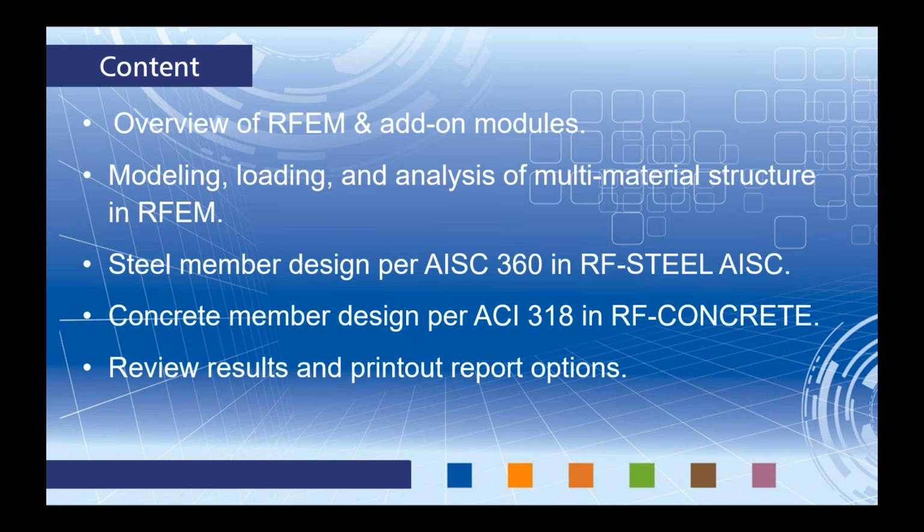Then we'll move into our add-on modules, and in particular, RF-STEEL AISC, where we'll be doing a steel member design per the AISC 360 standard. And in a similar manner, we will launch the RF Concrete add-on module, where we'll do concrete member design per the ACI 318. Lastly, we'll take a look at all of our results, whether that's in RFEM or these add-on modules, in a little bit more detail, as well as the printout report options, as I think this is one of the stronger features in our software as well.